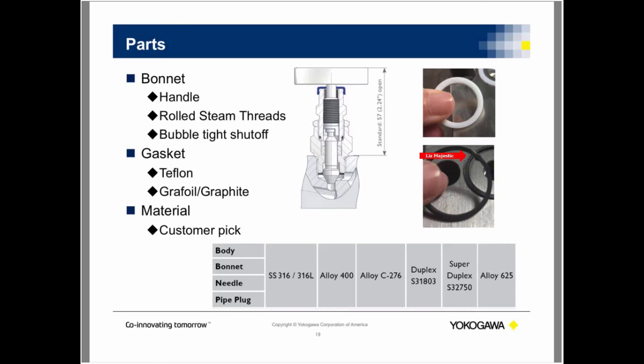So you want to make sure when you're putting this gasket in that you don't damage it at all, because you will see a leak. As far as taking them back out, they're kind of hard because it's kind of like glue. It's just hard to get right back out because it's compact. So that's the only disadvantage of having the graphite, is you're going to have to fight it to get it out, and when you put the graphite back in, you just don't want to break it.